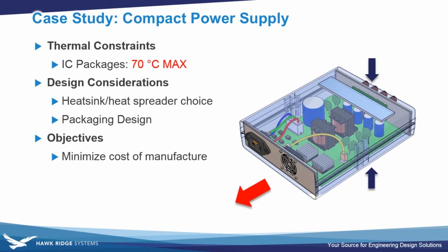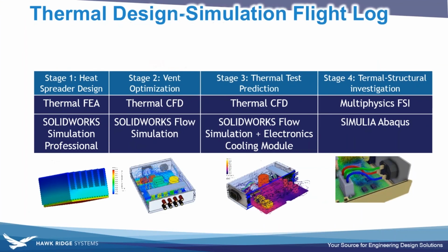Of course, if you want to start getting into design decisions that do heavily depend on the airflow, like where the vents should go or where the fans should go, you're going to need to move to a CFD tool, in this case SOLIDWORKS Flow Simulation. And Flow Simulation is a great fit for that application because it does the heat transfer integrated into the calculation. So in some sense, it does do multi-physics for certain types of problems, thermal and flow at the same time.